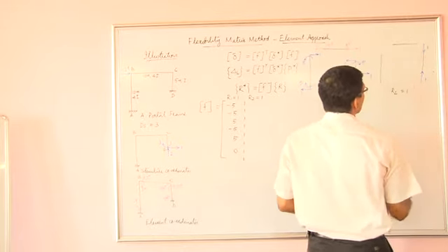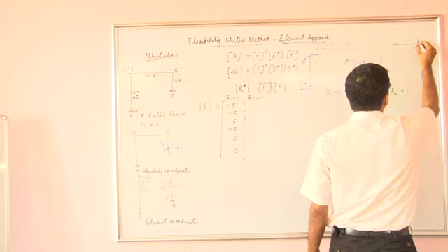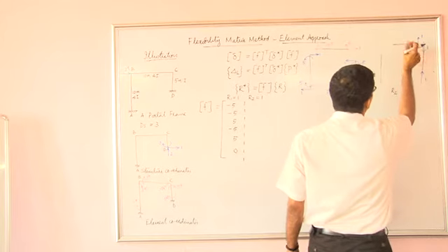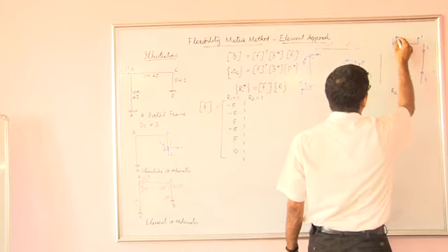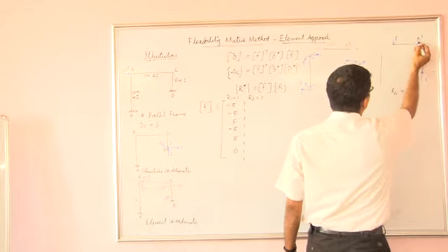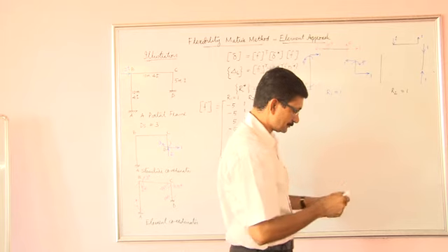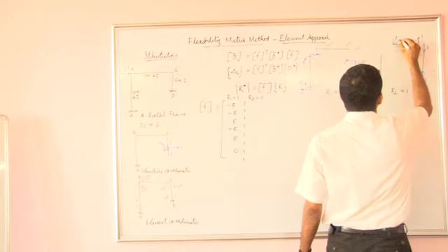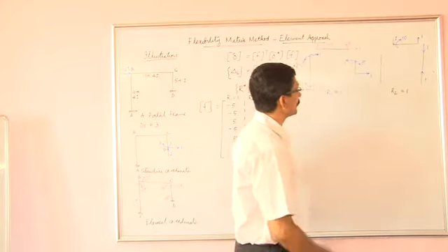That is fine. This joint net force is equal to 0, so the force over here would be upward and equal to 1. Further, for equilibrium of the beam, there should be a downward force at the other end equal to 1. Now these two forces create a moment of 1 into 10, that is 10 anti-clockwise, and to equilibrate that we require a moment of 10 clockwise. That is about the equilibrium of that beam.